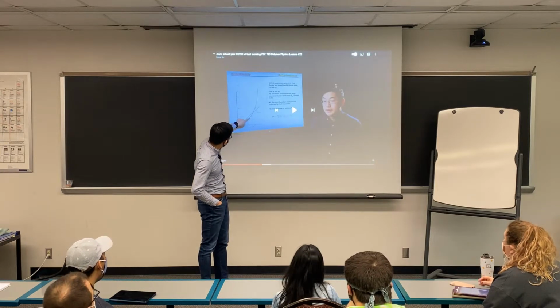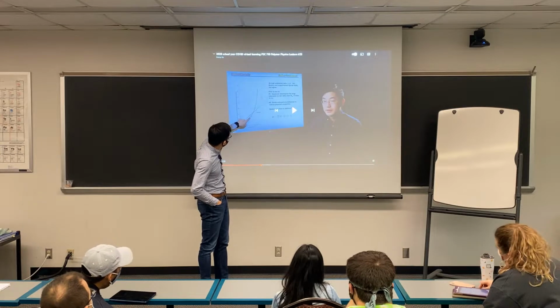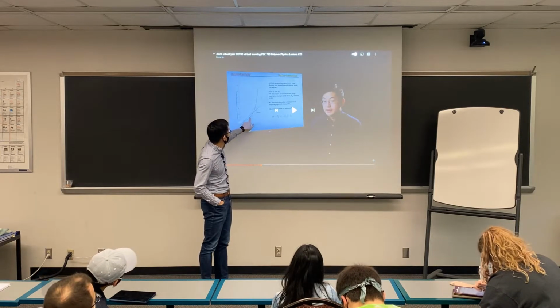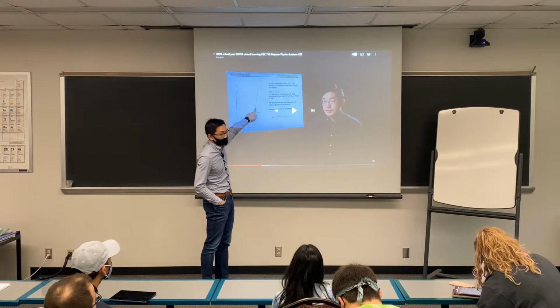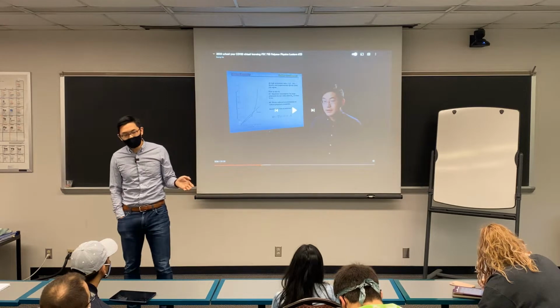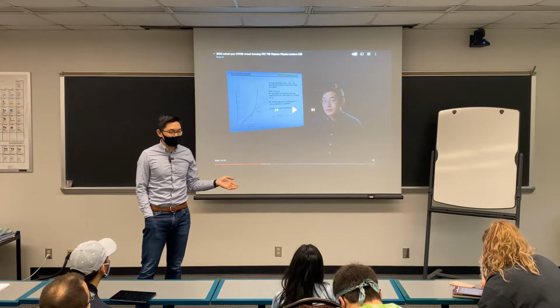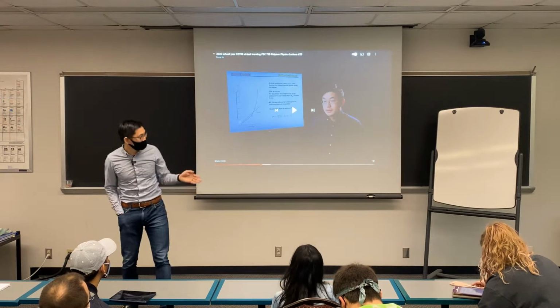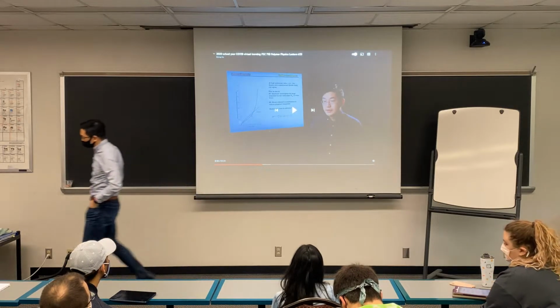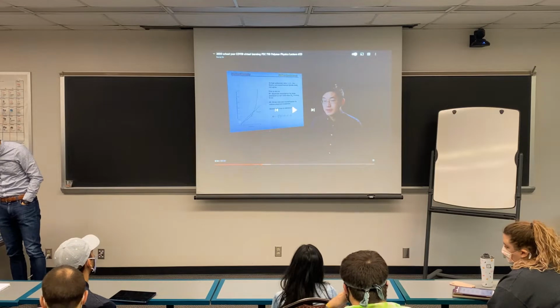Crystallization, I think, happens roughly about here. At a low degree of crystallization, it doesn't make a huge impact, but the more you stretch, the higher the crystallization is, and you will have deviation. So the Gaussian coil rubber elasticity theory doesn't consider that. That's one of the major reasons you lose theory versus reality at a high degree of strain.